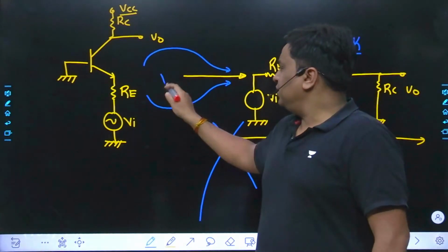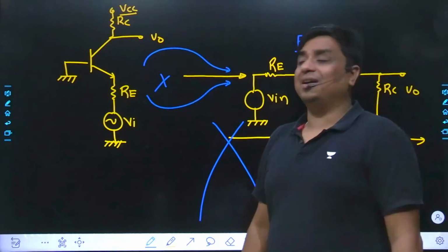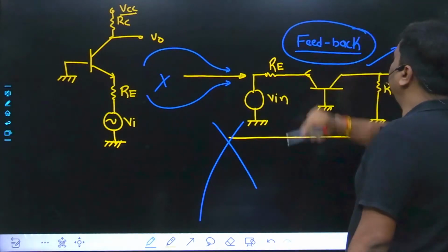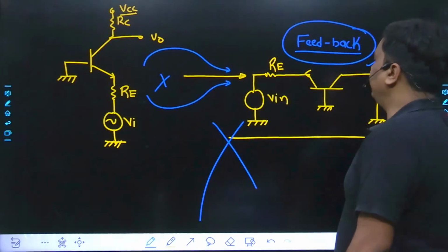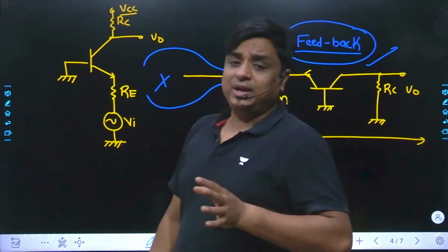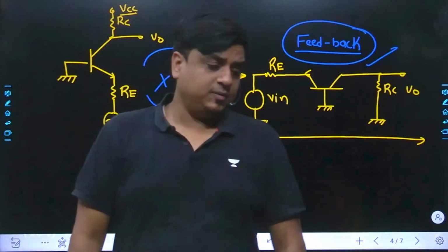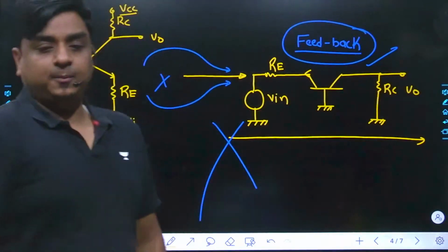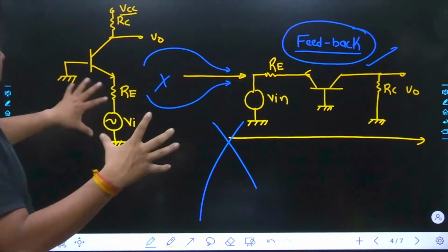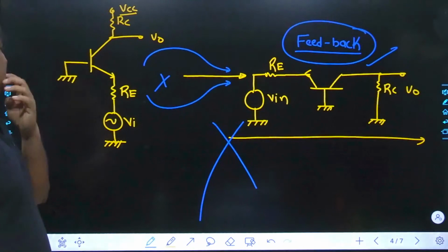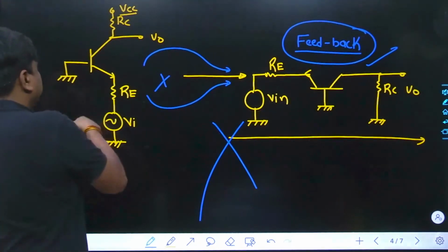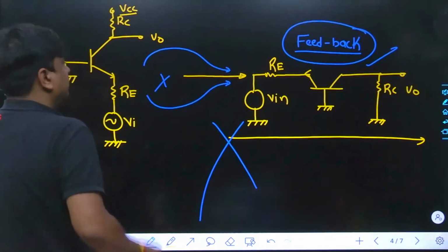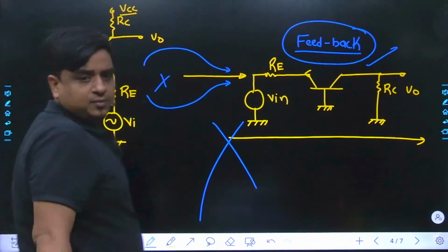But nowhere this kind of question would be asked, and if it would be asked, obviously you'll take its AC equivalent and you say there had not been any single element which might be bringing the feedback from output to the input side. There had not been any sampling point, there had not been any mixing point. Has it been clear? Ravi, has it been clear? But if you forcibly want to analyze this circuit as a common emitter, then you can say this current loop and this current loop would be falling through the RE, and I can say it has been a kind of current series feedback.